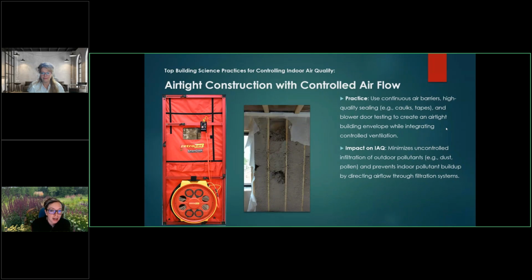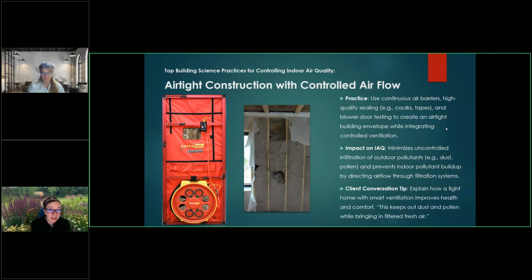And creating an airtight envelope while integrating all of your controlled ventilation, because once you make it tight, you need to provide fresh air for your occupants within the space. And then the impact on the indoor air quality is it minimizes uncontrolled infiltration from outdoor pollutants, dust and pollen, and prevents indoor pollutant buildup by directing airflow through those filtration systems. And I'll add to that, it also puts the ventilation where you want it to be.